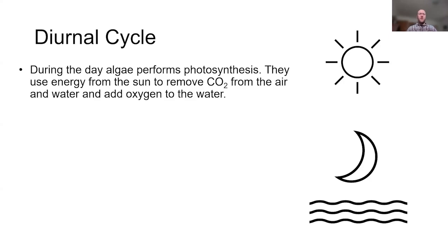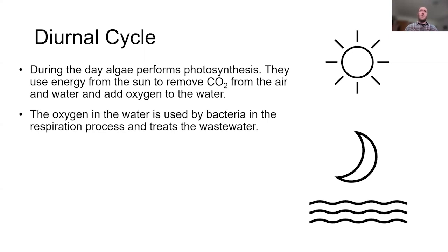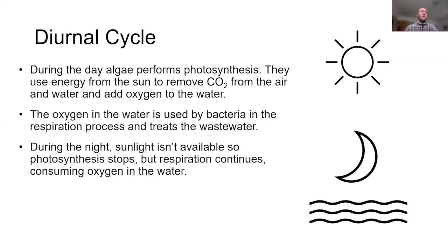Okay, so just to go over this process. During the day, the algae performs photosynthesis, so it's taking in energy from sunlight, and it is taking in CO2, both from the air and the water, and it's adding oxygen into the water. And so then that oxygen in the water is used by the bacteria for respiration, and it treats that wastewater. And then during the night, when sunlight isn't available, photosynthesis stops, but respiration continues. So that consumes oxygen in the lagoon.